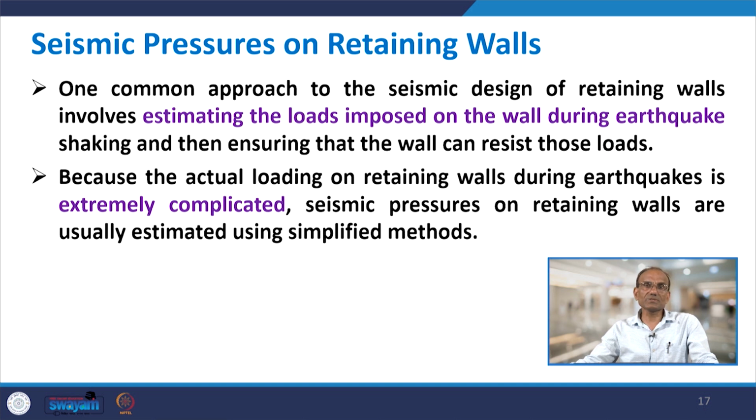One common approach to the seismic design of retaining walls involves estimating the loads imposed on the wall during earthquake shaking and then ensuring that the wall can resist those loads. So, this is the way, like in the static case also, we said the design will not be done based on the deformations; rather, the design is done based on the forces and you assume some factor of safety, so that the deformations are within the permissible limit.